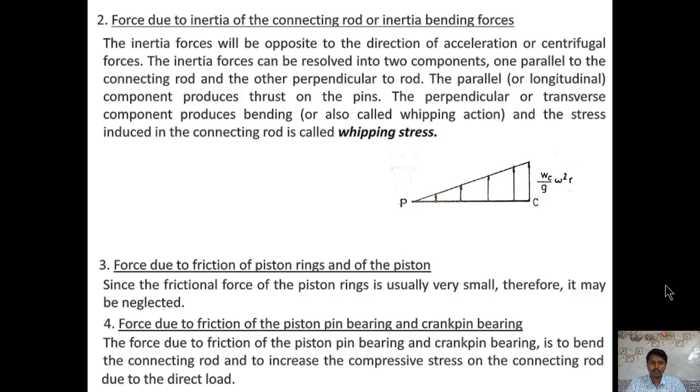The second force is the force due to inertia of the connecting rod. This force, or inertia bending force, arises because of the motion of the connecting rod. Whatever stresses are induced on the connecting rod are called whipping stress, because the action is like a whipping action.